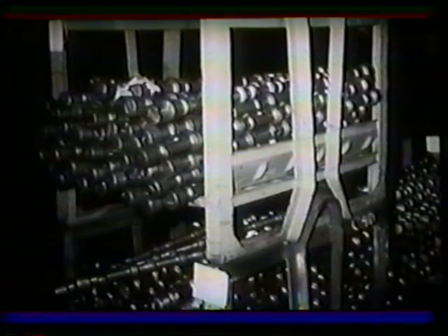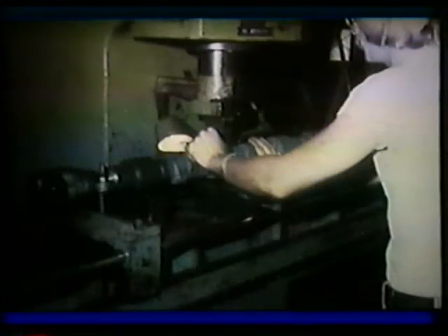As you can see, camshafts begin as rough forgings or castings. Once the rough camshafts are received, they are machined and heat-treated. First, the sides of the lobes and the thrust grooves are machined. Then the main bearing surfaces and lobes are rough-turned.